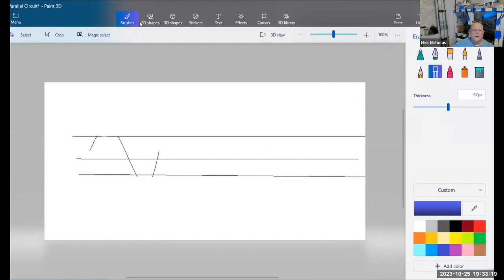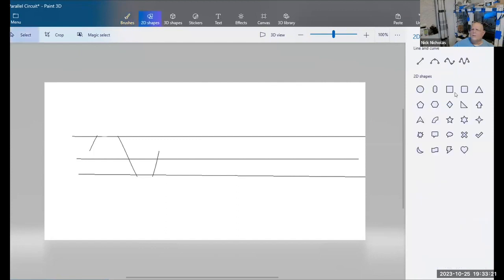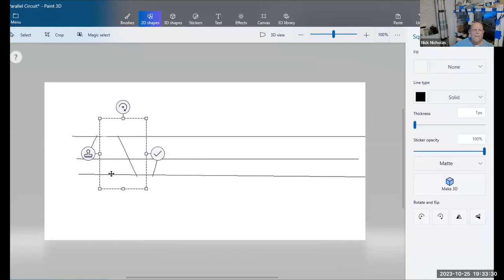The receiver at the other side can only see a window so wide, and that signal might be too wide for it. If this is its band, as much as it can see, it's going to be missing part of the signal because it's out of its range. It's also going to hear the junk that's being transmitted. You're not doing yourself any favors.